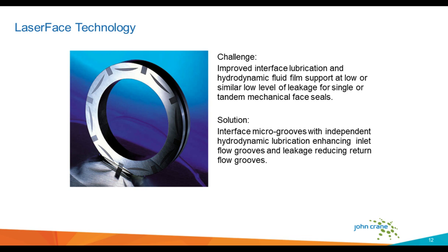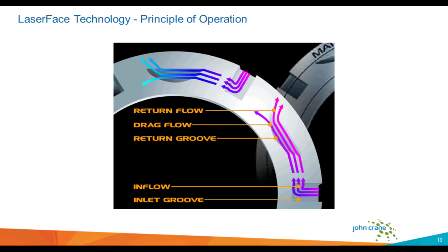Now, if we look at that picture over here, I would like to explain more on the functionality of the laser face. The laser face pattern combines a pair of symmetrical, precision-machined microgrooves, typically a few micrometers deep. They're not as deep as Hydropads, and each performs a different task. The square inlet groove is normally connected to a pressurized fluid area, and through it, the process fluid can penetrate deep into the sealing interface.